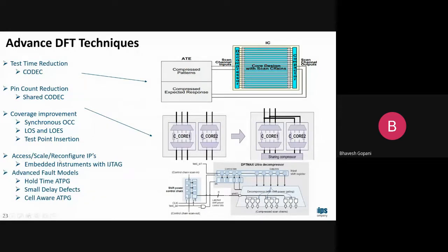If we are still not able to detect faults, we can try test point insertion. And IJTAG is definitely an advantage if we enable or disable specific IPs. If we don't want them included in a chain, or we can save power for those IPs. Let's say those IPs are hard macros, very well tested, and functionally covered, then we can exclude them from the scan as well.